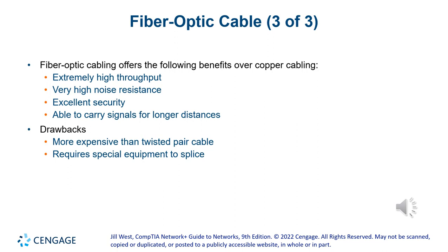That provides security because now you cannot tap into it. If you tap into a wire, there are electrical devices that can sense the pulses of electricity going through the wire, and they can put a tap and just listen to that communication. On fiber, you can't have that. There's no way to clamp something around the fiber and capture any light going through. And then the distance.